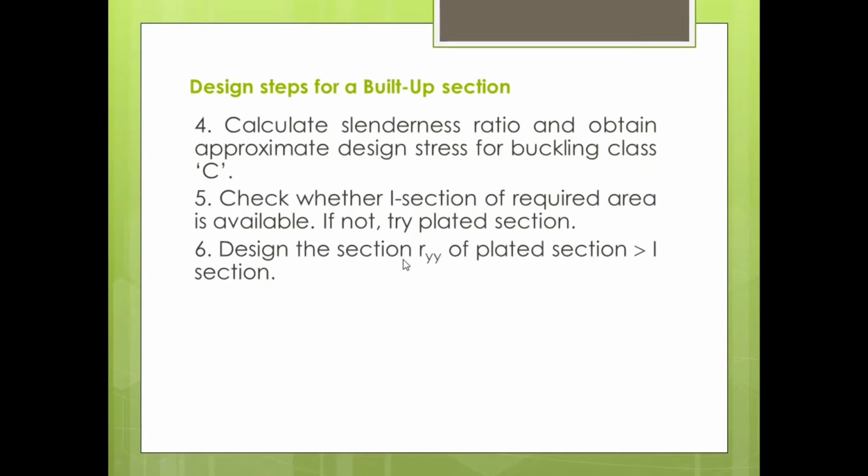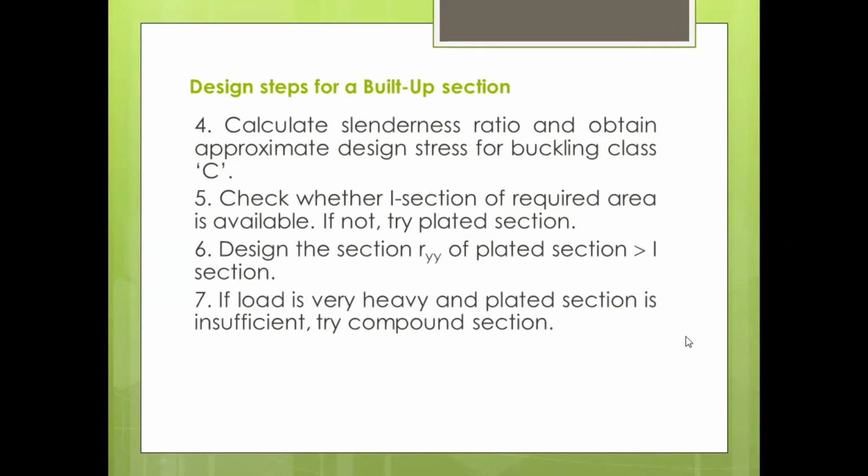Okay, it means the compound section will have a different RYY value, and this should be more than the RYY value of the I section selected from the table.